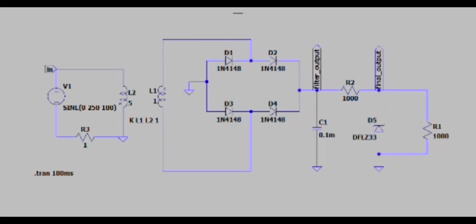When the voltage across the zener diode is lower than the zener voltage, the zener works in a reverse bias region and the voltage regulation will not occur. When the Thevenin voltage across the zener diode terminal is larger than the zener voltage, the zener diode will act as a voltage regulator to maintain the voltage across the zener diode at the same level as the zener voltage. So a constant DC output will be produced. So this is my presentation about the design principle for our circuit.